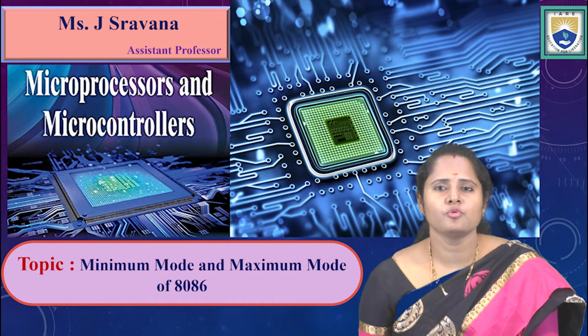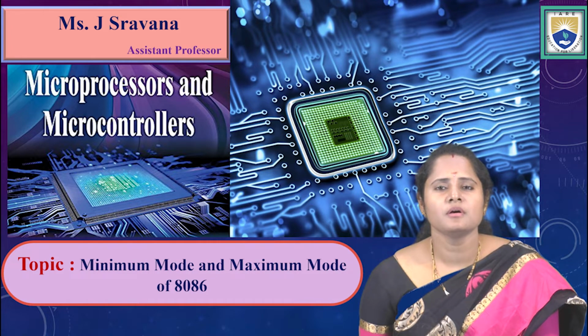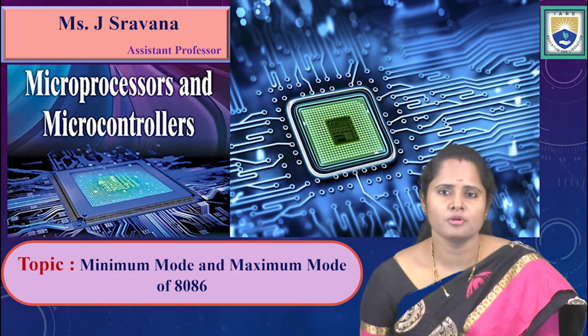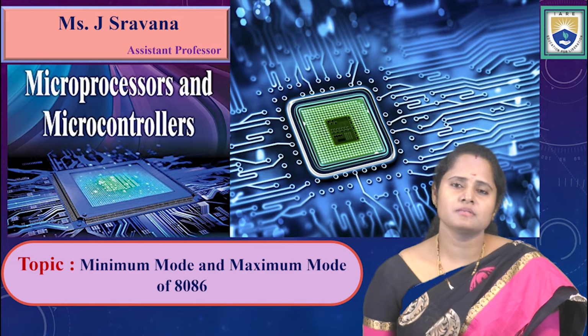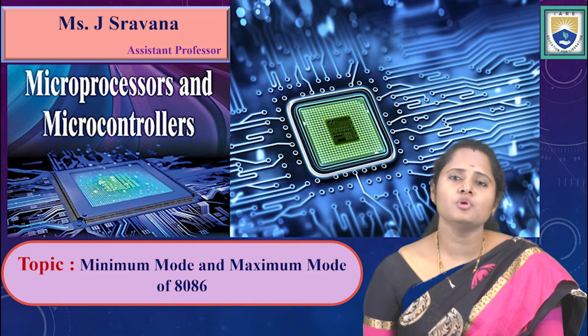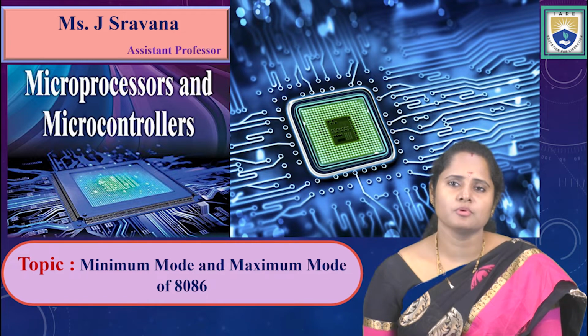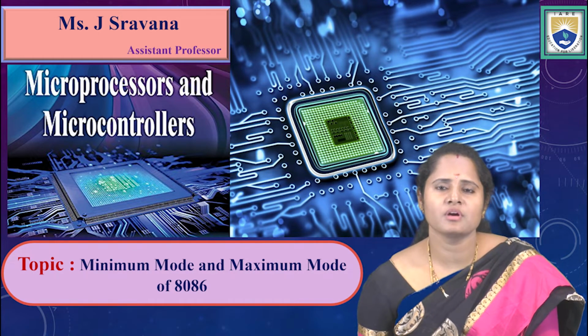What is a maximum mode? It is when you are connecting more than one device or more than one processor to the main processor, then it is called a maximum mode. So 8086 has one special feature, where it can work in two modes: minimum mode and maximum mode. Now let us go through how the minimum mode functions and how the maximum mode functions.